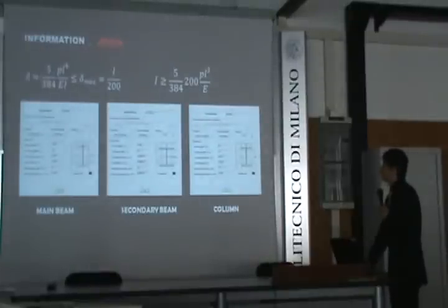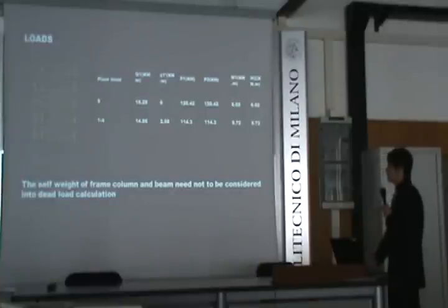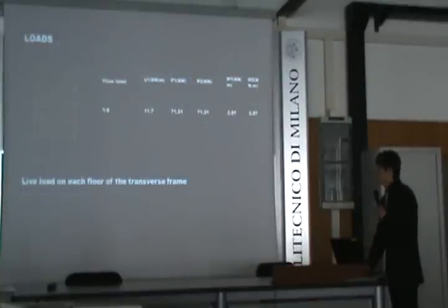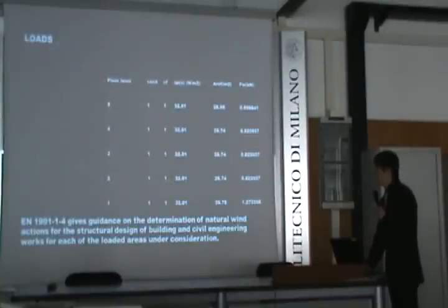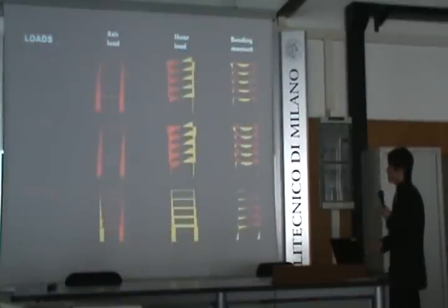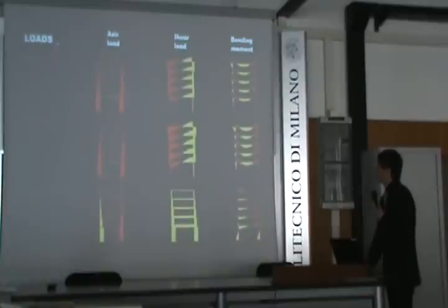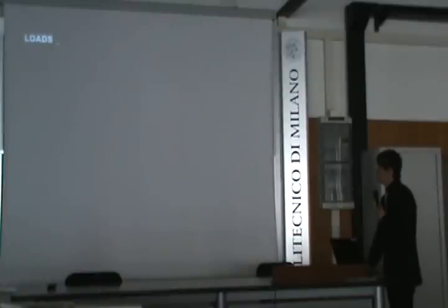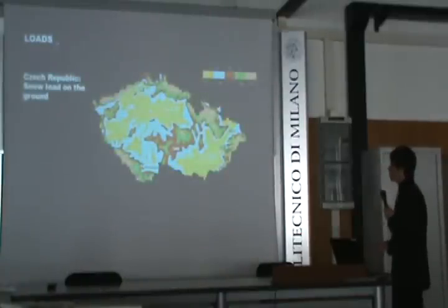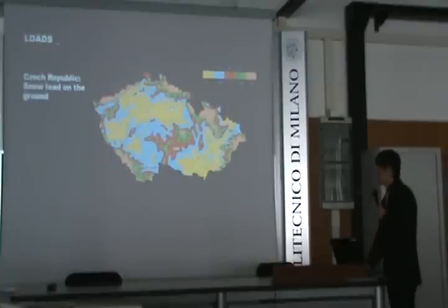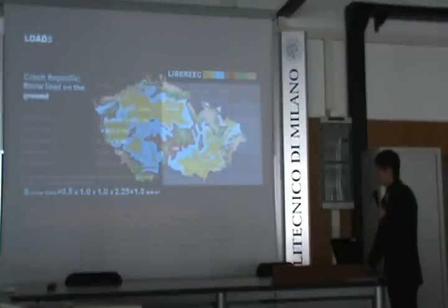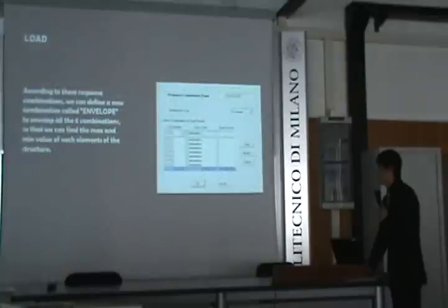Then, for the pre-design of the structure, these are the basic data of the dead load, live load, and the wind load. Then I will put these data into SAP2000 and get the diagrams of axial load, shear load, and bending moment. I also need to calculate the snow load according to local building codes. Then get the load combinations.